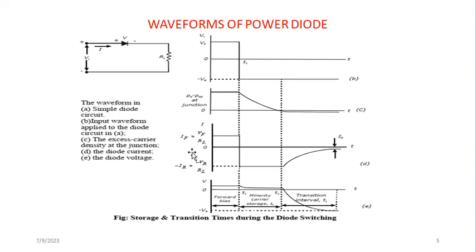And here is the current. Whenever the input waveform is positive, that is high, the current is also going to maintain that high value. When it suddenly drops to negative, the current will also change, but after a very small time, it will start increasing because of the small minority charge carriers we talked about, until it reaches a point where we maintain a very small amount of current, and that current is what we call the reverse leakage current or the reverse saturation current.